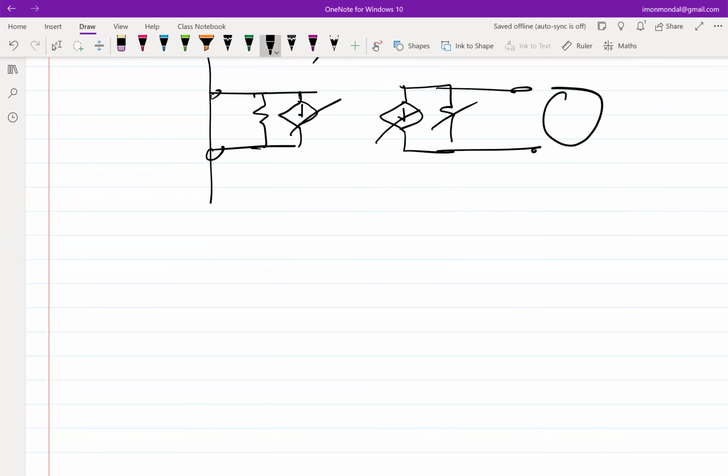Fine. So this is as far as I wanted to talk about S parameters. Another reason I wanted to talk about S parameters is because in the assignment, you will see that I have talked about using S parameters analysis to find impedance. That is useful. You can do the analysis the old school way also, because in simulation, you don't need to bother about these long wires. You can basically connect impedances directly and find out. It's going to give you correct results. There's no two ways about it.